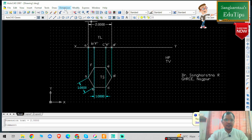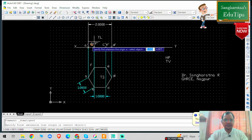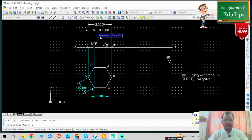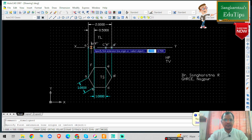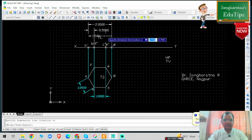Okay, similarly go to dimensions, select align, click this particular point, this particular point. This is basically my 0.5 AutoCAD unit, that is 50 mm. Similarly going to the dimension, select align. Okay, this particular point A dash and this particular point C dash E dash. Okay, and this is basically my 1.5 AutoCAD unit.